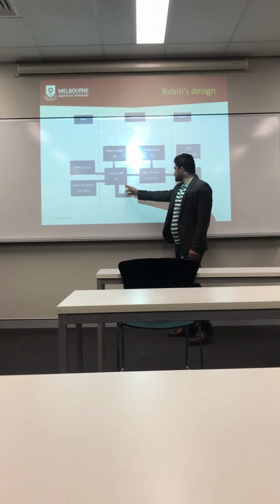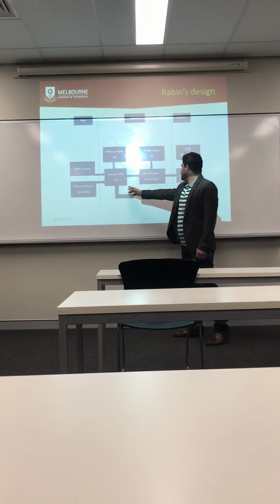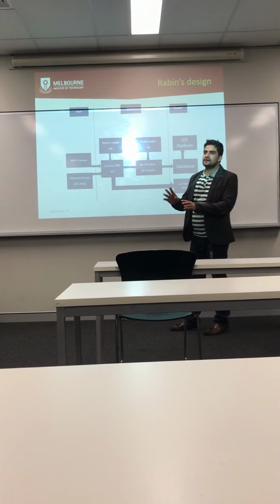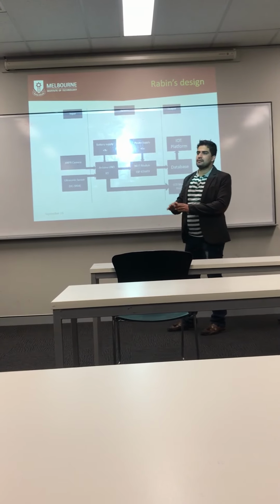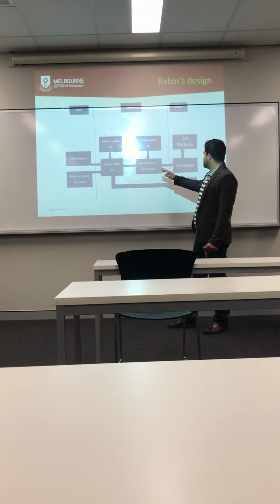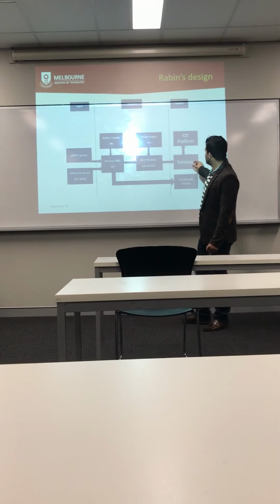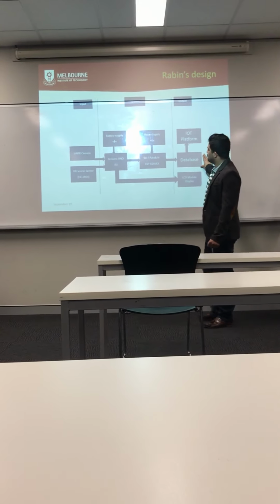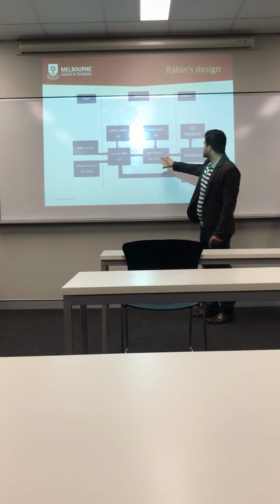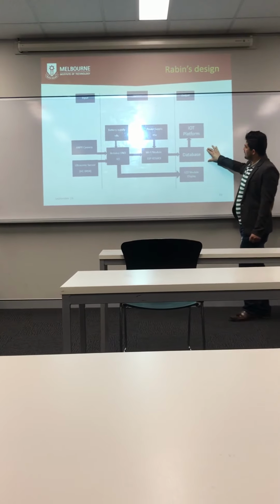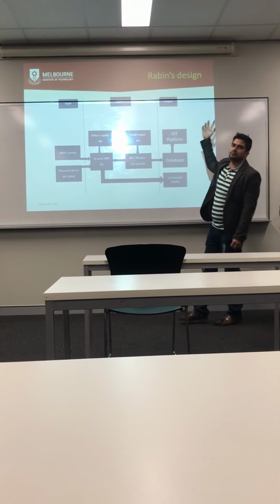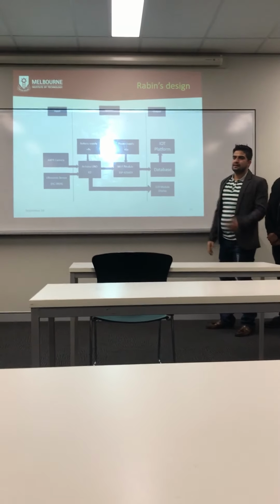After that, the Arduino will provide information to the LED display module, showing whether a parking slot is available or not. The Arduino also provides data, which will be stored in a database with the help of a Wi-Fi module, which gives the Arduino access to the internet. After this, the database will provide information to the IoT platform, like mobile or laptop.